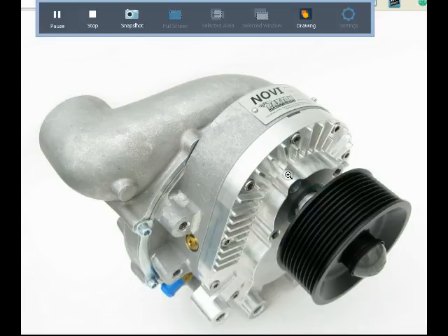So the turbocharger, you know, now they're automatic wastegate actuation, so you won't overboost and burn your turbocharger out, but still you're going to require some maintenance on the turbocharger more than with a supercharger, because you also have oil going through it, you have the heat, and eventually you're going to have more wear and tear on the turbocharger over the course of time, so there's going to be more maintenance involved.